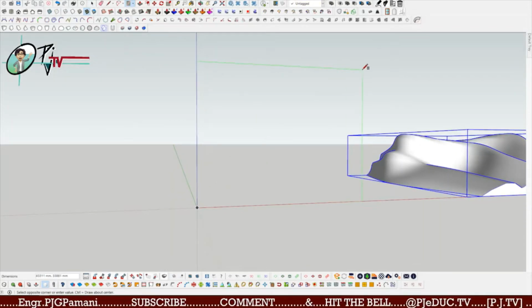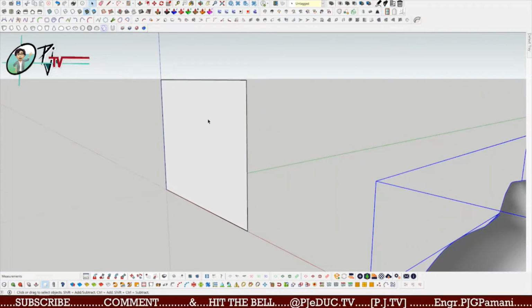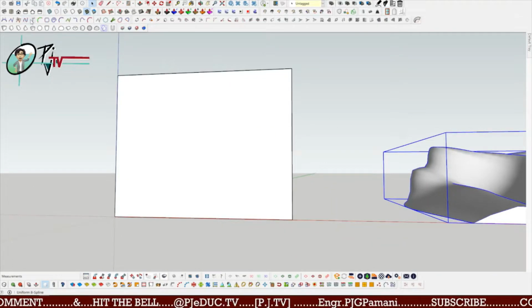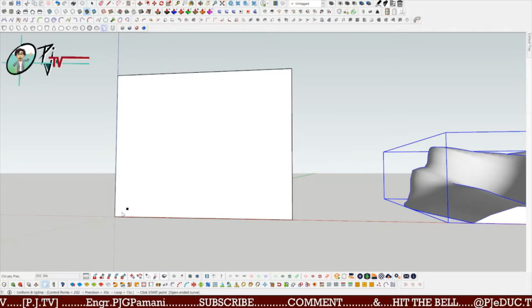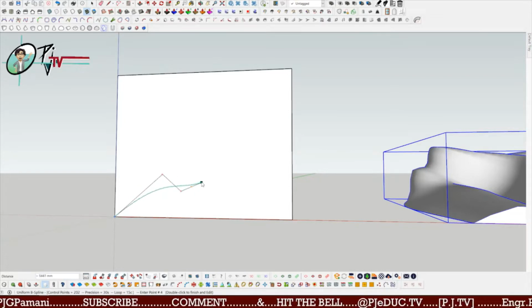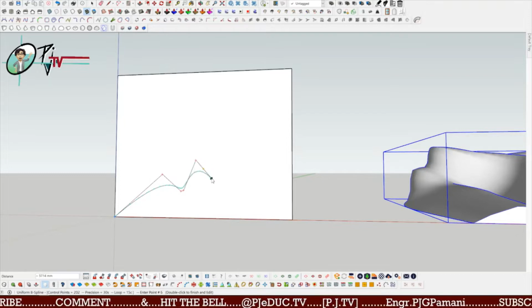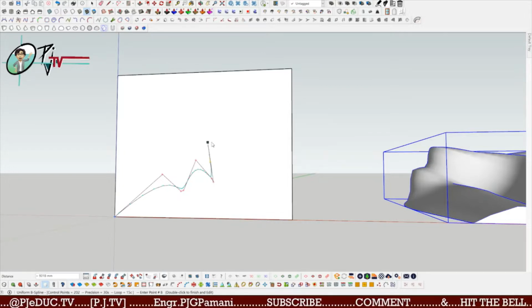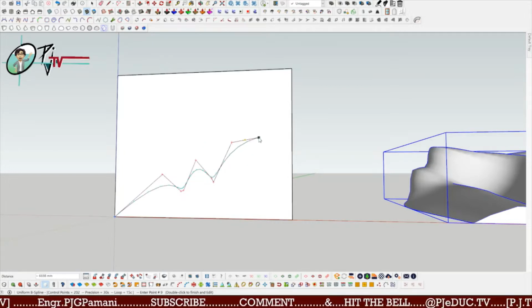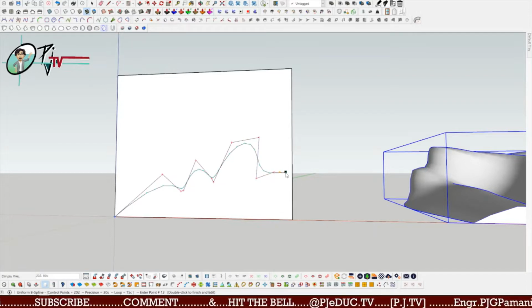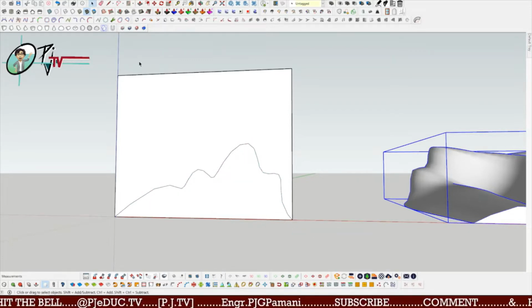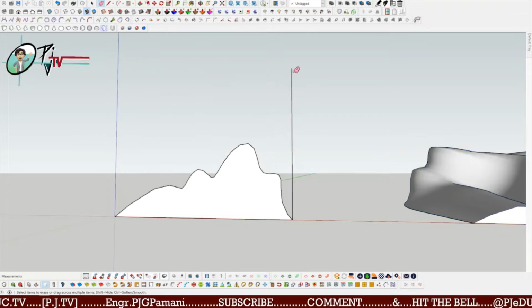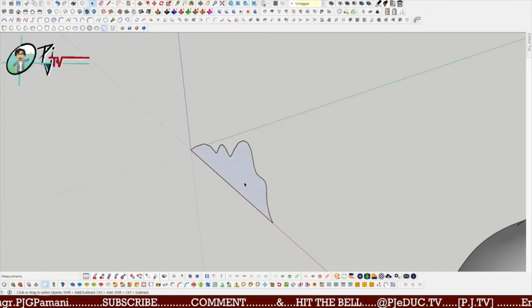First is for us to draw a rectangle. Any dimension would do. This is just for a reference. Using Bezier spline at 5 angle points. Create our sections. Then right click to exit. Erase the unnecessary sections. Then create again. Put it in a group.